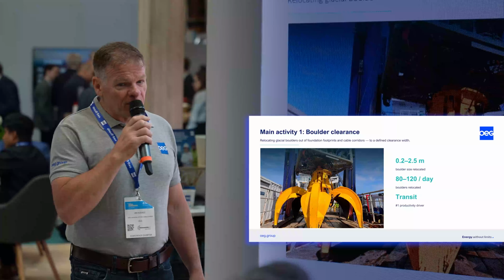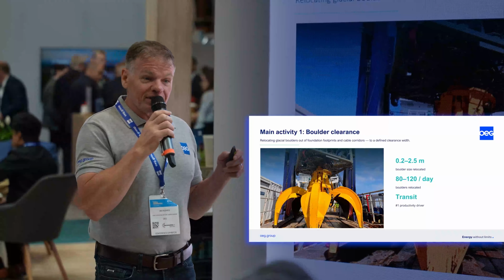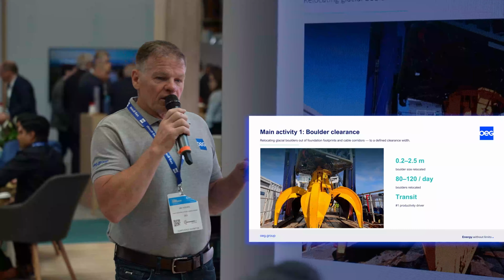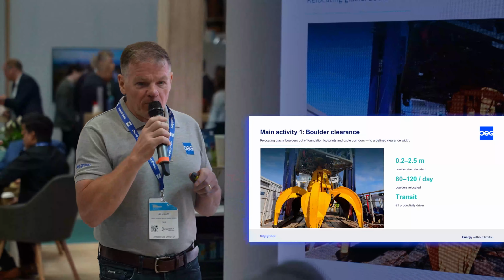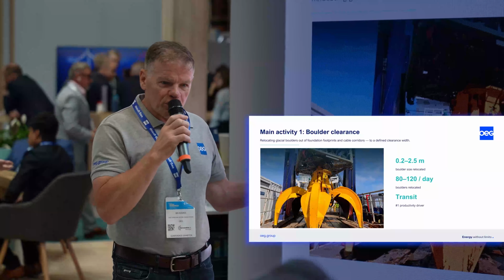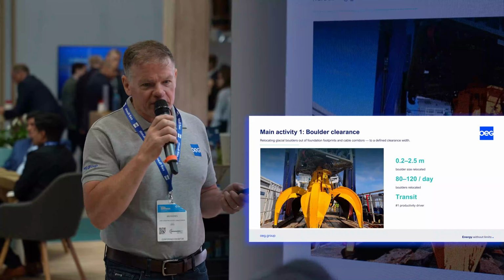The biggest factor as part of that is the actual vessel transit. Vessel transit is ultimately what dictates how many boulders we can clear per day. We have gone on sites where they say, we want you to move a boulder 100 meters away. If you think, you're moving the vessel backwards and forwards 100, that's 200 meters each movement for each boulder. We say stick to 20 meters outside.